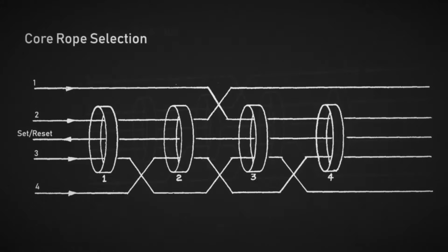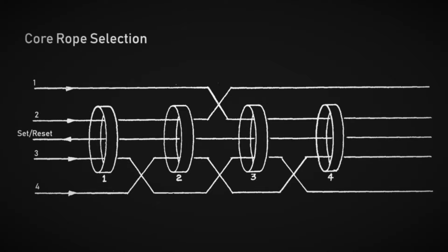For the sake of simplicity, let us assume our memory is composed of only 4 cores, which are all made of a special ferromagnetic alloy, called permalloy. They are not permanently magnetic, but as I said, they can be magnetized when current flowing through the set reset wires create a magnetic field. In order to magnetize only one of the cores, there are so-called inhibit lines, which prevent a change of magnetization in the cores. Now, let us change the magnetization of core 1.